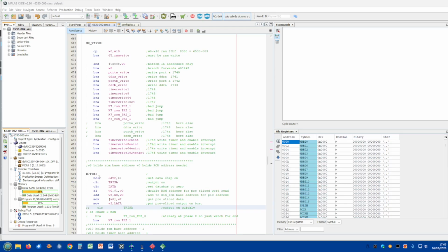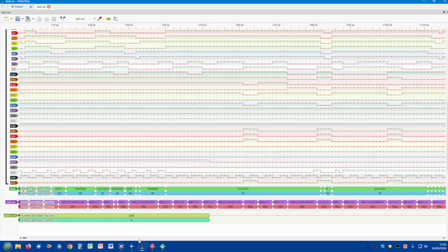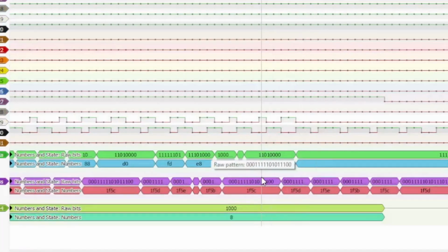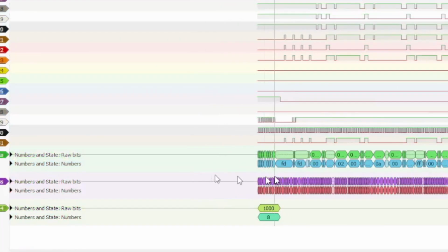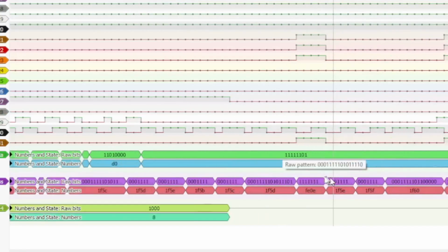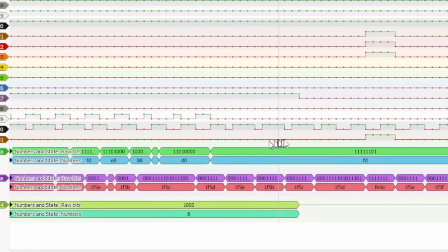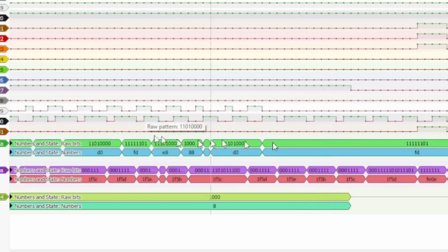It sets it to 0, and that enables the input or output IC on the bus. Now, I just ran it, and it crashed. And here is where we get the crash where the data bus sticks. And this one at the bottom is just the trigger that caused it to happen, and the pre-trigger.